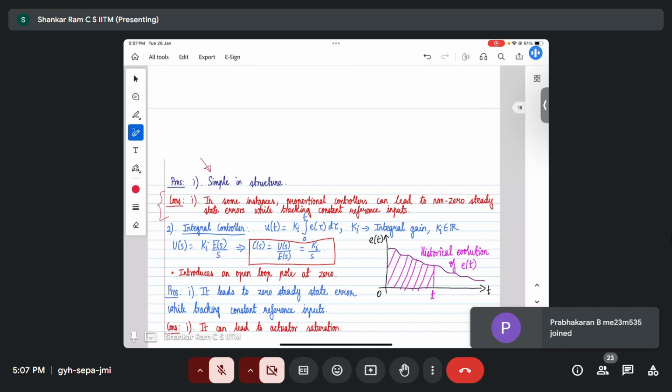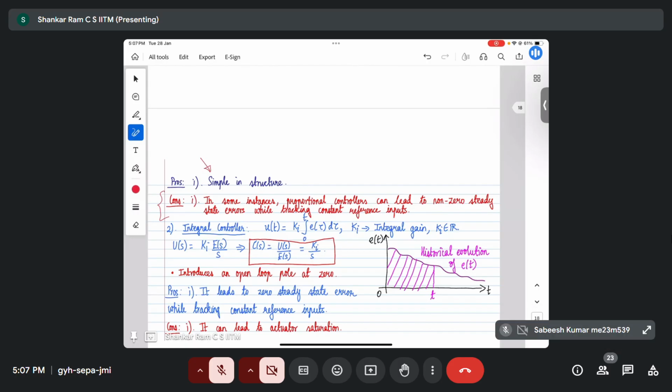When we have only purely proportional control, not always, but in some cases, we can have non-zero steady state tracking error. So that's what may happen with pure proportional control. Then what are the other choices available? Of course, one would typically start with proportional control. If it works, well and good, right?